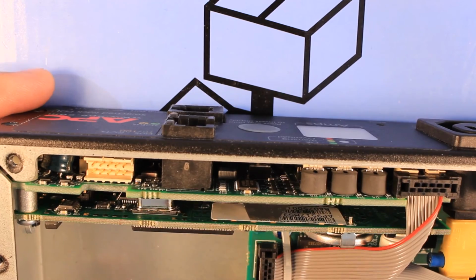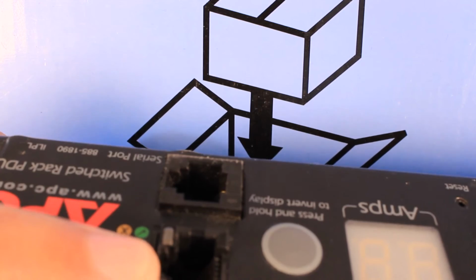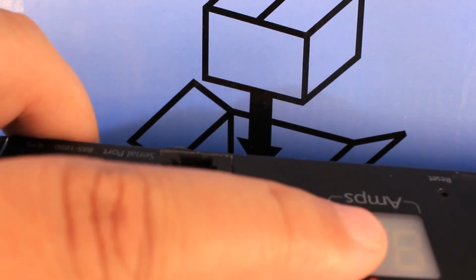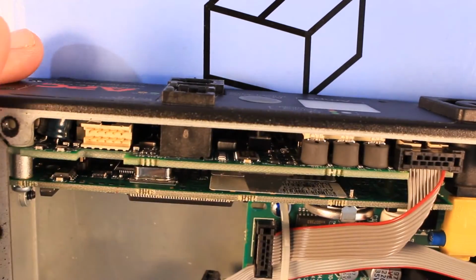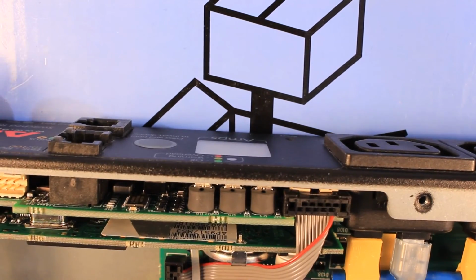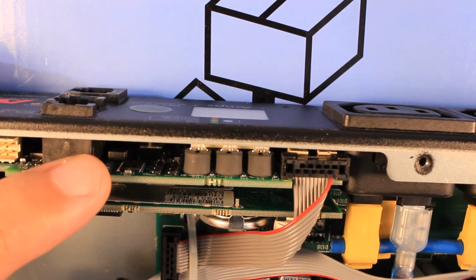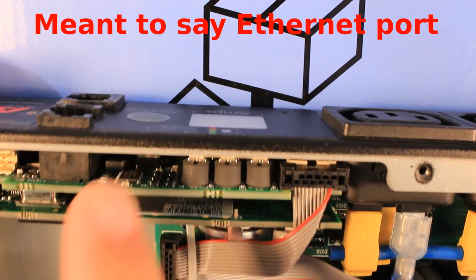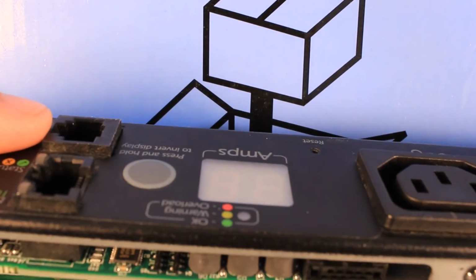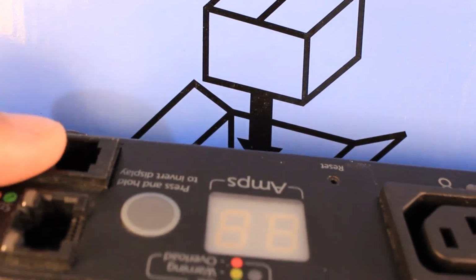This front board is connected to the I/O, so to the 10/100 megabit Ethernet port and to the serial port. It has the button and the 7-segment display, the 3 LEDs which I mentioned at the beginning, and of course it also has the PHY, or the physical input-output chip, for the serial port, and the RS232 conversion chip, most probably a MAX232 for the serial.